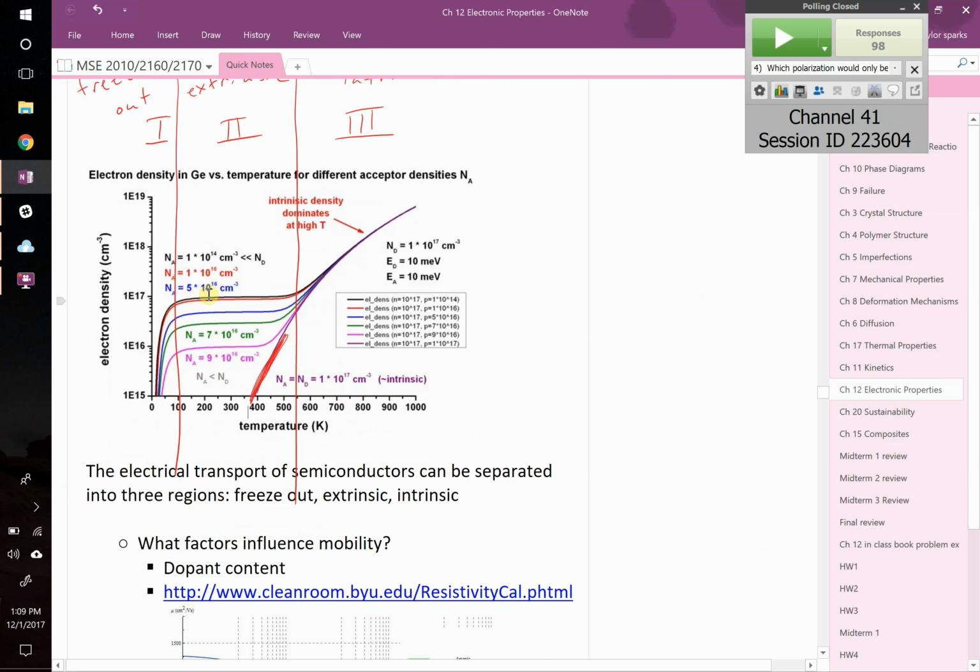These things are doped, and basically if you look at the numbers here, they're doped at higher and higher concentrations, right? So the more that you dope it with, you're increasing your carrier concentration. So technically what Brandon said is right. He said, technically because this curve should increase over all temperatures, your conductivity should increase over all temperatures. But what you're seeing is that practically speaking, there's a region in the middle where it doesn't increase very much because its contribution is still so small. Okay?